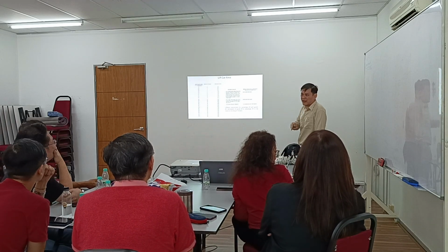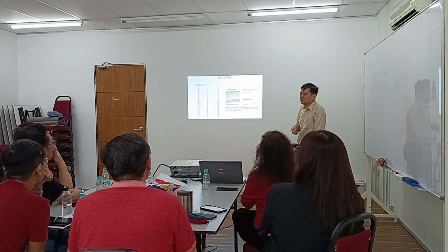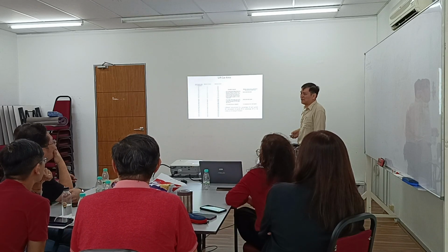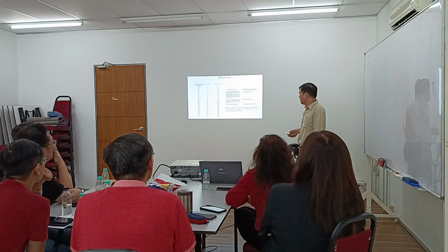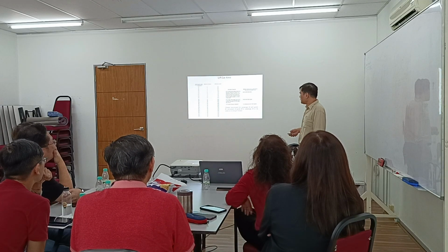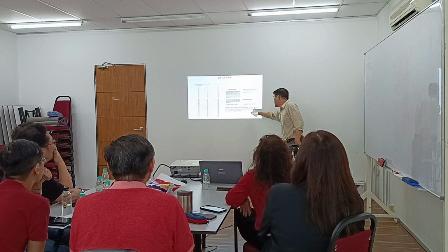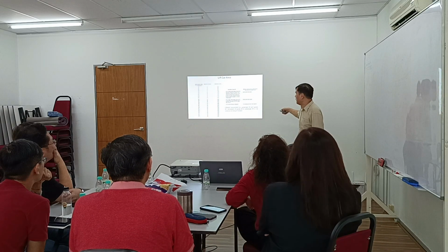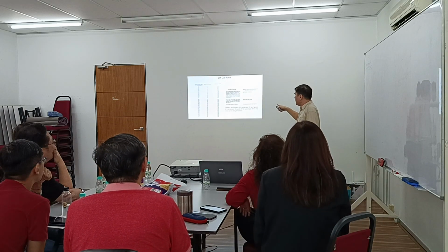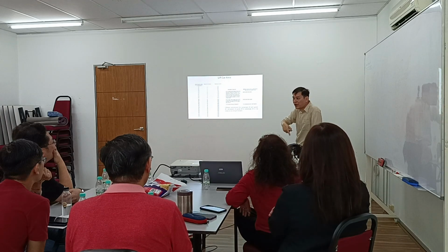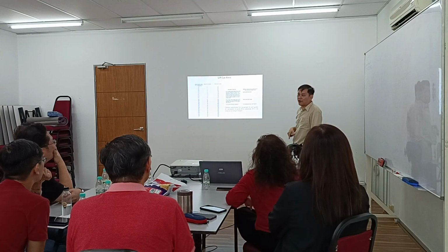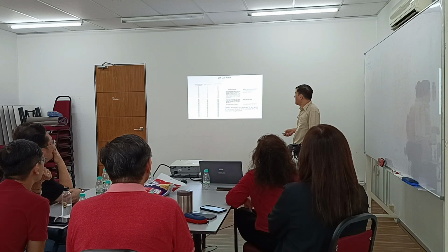But I think for the consultant, usually they will refer to the lift manufacturer's catalog. There are different requirements for passenger lift and goods lift. As I mentioned just now, conversion of a goods lift to a passenger lift or vice versa is not straightforward because the floor area is different.